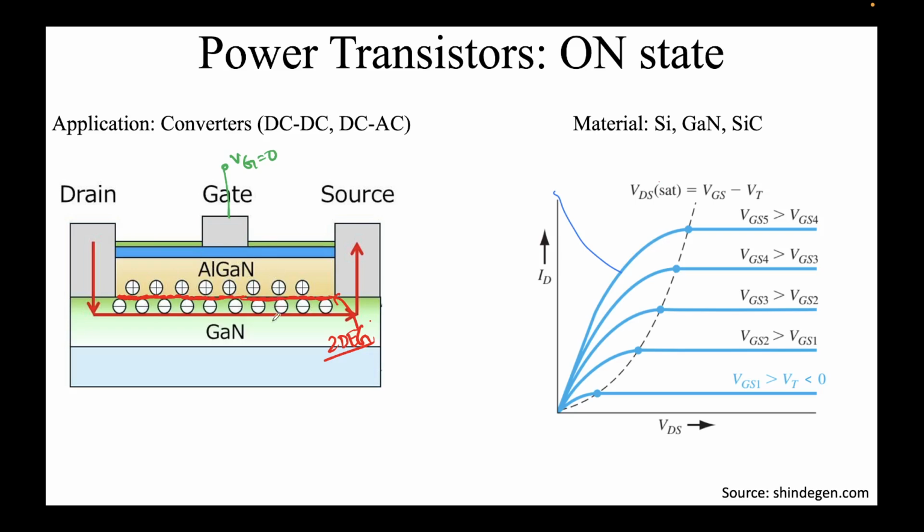But what essentially is happening, even though the epitaxial stack is different, because there it's only silicon and then there was an oxide, right? Here you can say the silicon counterpart is gallium nitride and the silicon dioxide counterpart is aluminum gallium nitride. There are other layers as well, but I am just trying to be as close to the MOSFET as possible, and at least you can appreciate that the nature of the behavior will be very similar to what we have in a MOSFET. So this is the output characteristics from one of the slides of the MOSFET session. This is taken from that itself. I have not changed anything. I just copied it as it is.